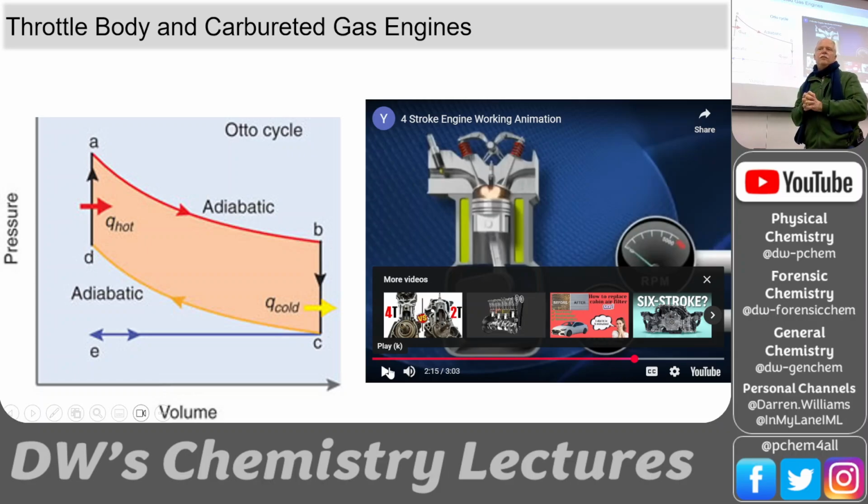Now, sometimes with smaller engines, you can hear the individual explosions. Most lawnmowers are single piston engines that have a flywheel. And so you pull on it to get it started, and you're trying to get some intake, and you're trying to get a spark, and it pops, and it's enough to get it going. But if it's a cold engine, the gas doesn't have a good vapor pressure. You've got plenty of air, but you don't have a lot of gas vapor, because it's cold.